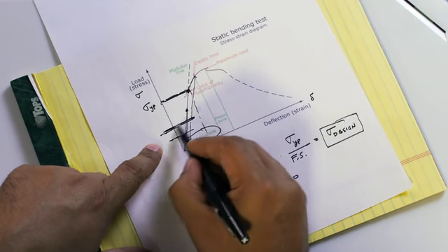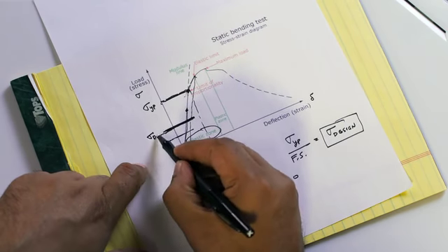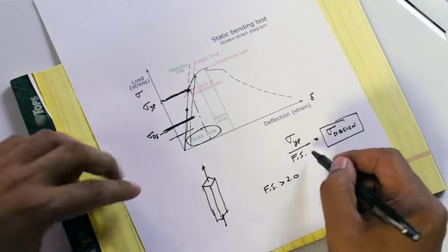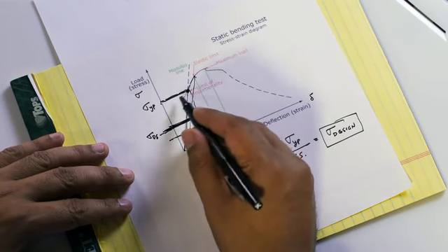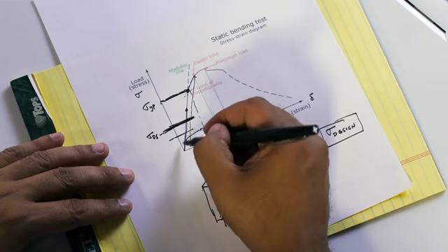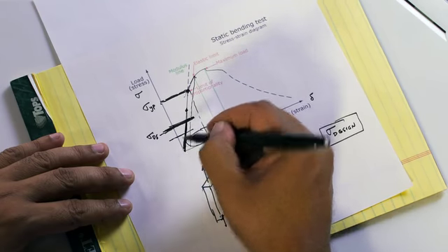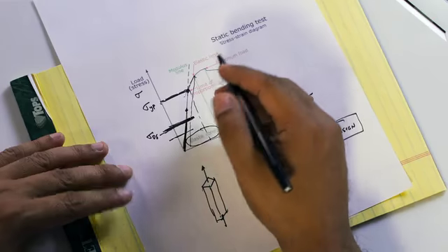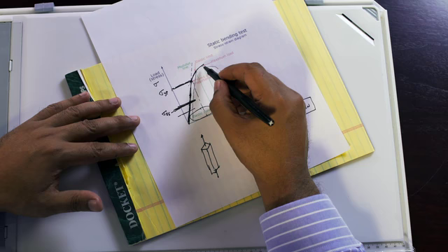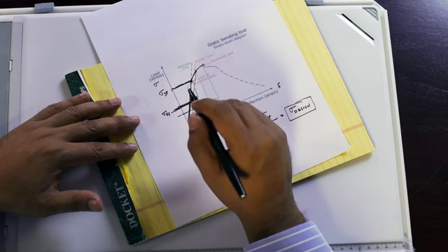So by limiting our design stress, let's say we're using a factor of safety of 2. That means we're only using about 50% of the yield point capacity. So the entire structure will always perform in this envelope. And then maybe in some dramatic situation it might go beyond that, in an earthquake, in a hurricane, or in a tornado, and in some very, very extreme circumstances it may actually break. It may actually go all the way here and it'll tear. So we try to prevent that from happening. And so that's why we have factor of safety.